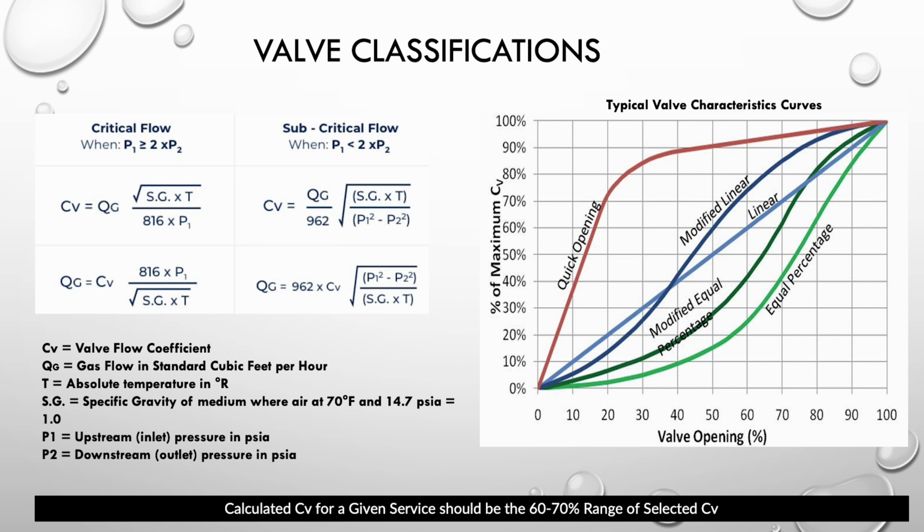So, as we mentioned earlier, it's driving force, flow, and conductance. But that brings up two more categories. If I'm dealing with a critical flow, the downstream pressure does not matter anymore, because you are in a sonic case, you're at sonic pressure. Before you get too deep, can you explain the difference between critical flow and subcritical flow?